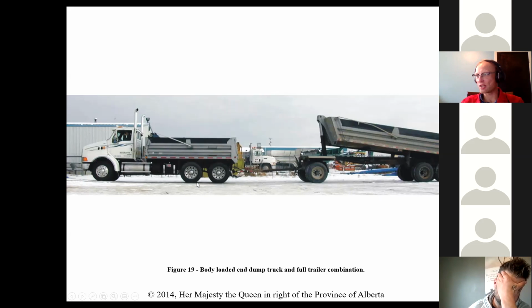You got to grease them too, so that's another grease point to be aware of, depending on what you're servicing, right? There's lots of common grease points that we all are aware of, but sometimes depending on application, you know, like rollers on a deck or turntables on a full trailer like that. So things to be aware of would need lubrication and maintenance.